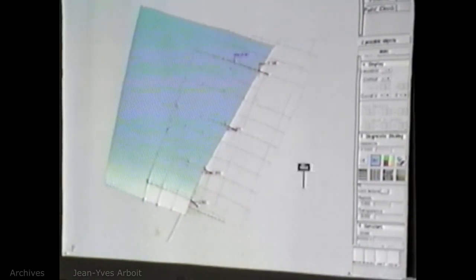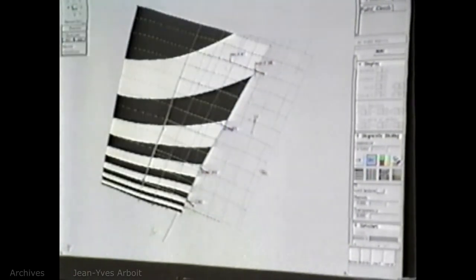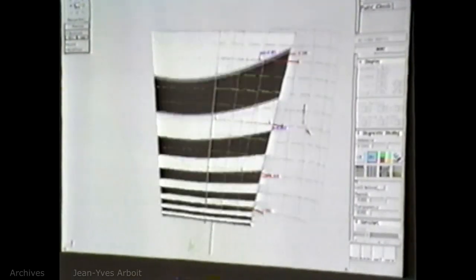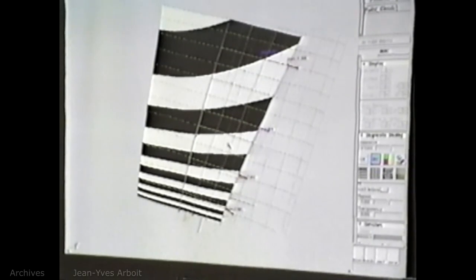Now you have visual symmetry across planes within your layers. The reason I modeled it that way is so I would maintain symmetry across center line. Now, one thing, we can enforce it tangent-wise, but we can't enforce it for rate of curvature across center line. That's something that ICEM Surf can do, but for right now, we have to do that by actually modeling with the third row of CVs, so that you get a curvature comb plot that goes across center line and